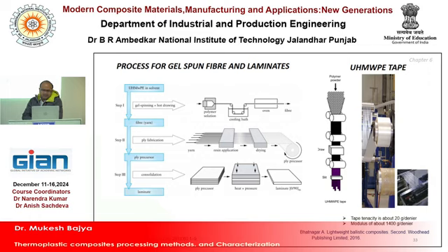In that case you can see first you are using a UHMWPE polymer, then you need to make the fiber. That is not a fiber, basically I will say filament, because the fiber terminology is generally used for small quantity entities of the material, and the filament in that case is the continuous fiber. Then you need to prepare the ply precursor.